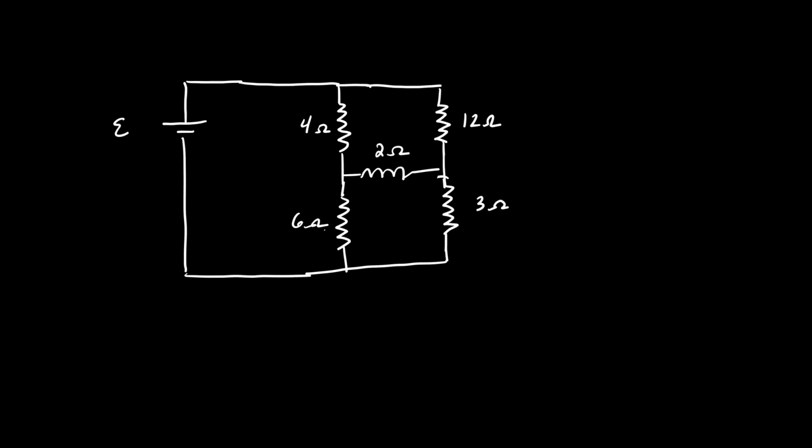But that's not what most circuits are going to look like. Now, in this class, they're not going to try and throw at you something like this, but the only way to solve this is by applying Kirchhoff's rules or some modification of Kirchhoff's rules and generate relationships. Now, I want you to look closely at this. The number of equations you would generate is actually pretty high. Every junction generates its own set of current equations.